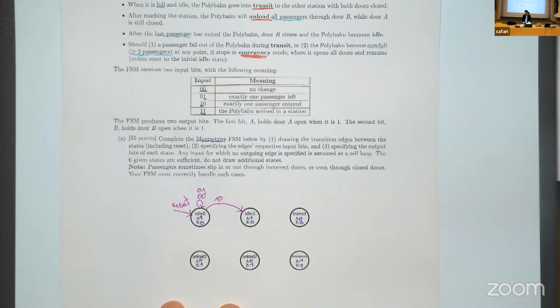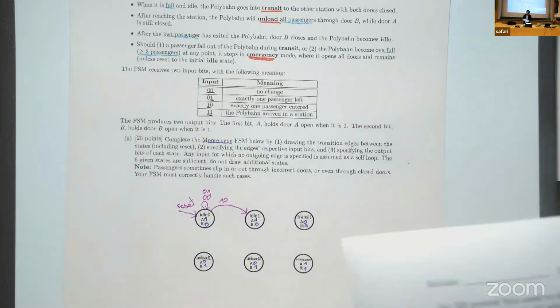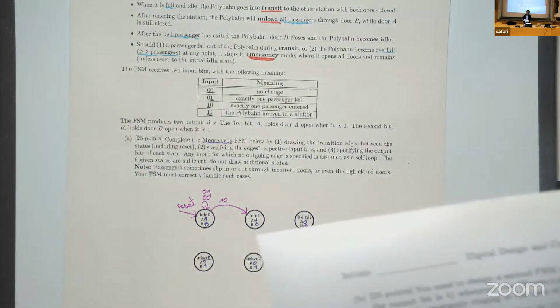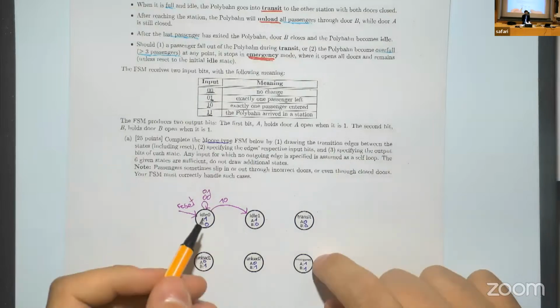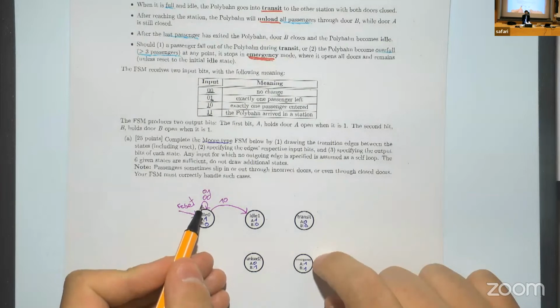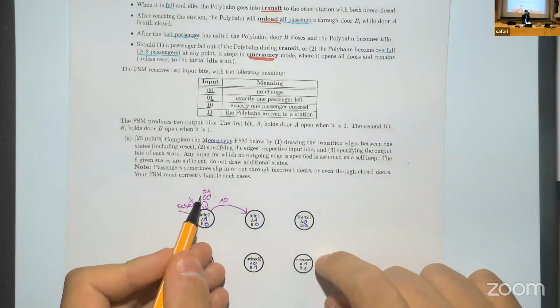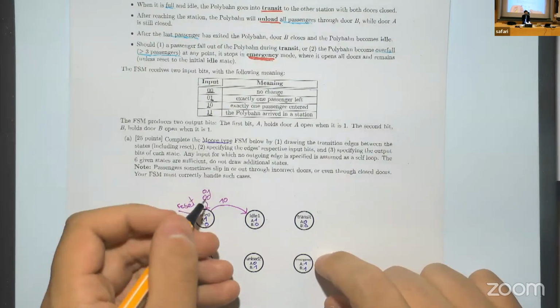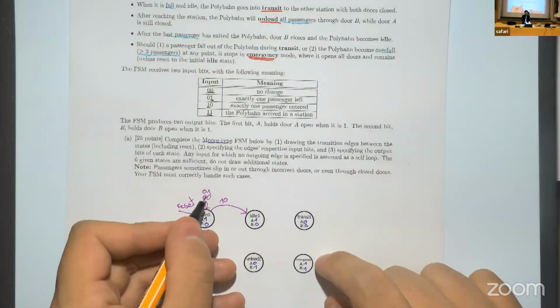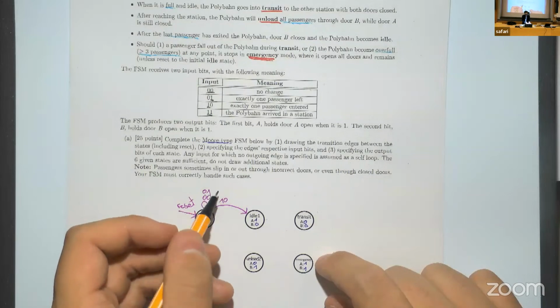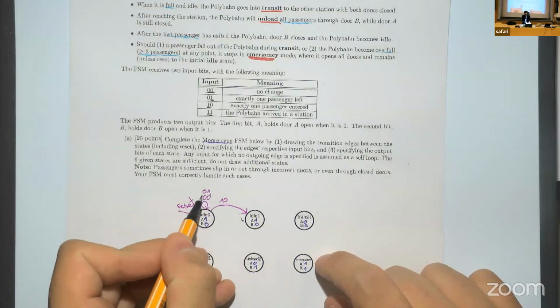I guess it gets a bit more tricky in the Mealy type FSM. You need to be a bit careful with the output bit so you don't confuse input and output bits. Yeah, all right. So basically, it's fine to essentially ignore states that don't make sense or edges that don't make sense, but you should define them in some way. And okay, let's continue here.